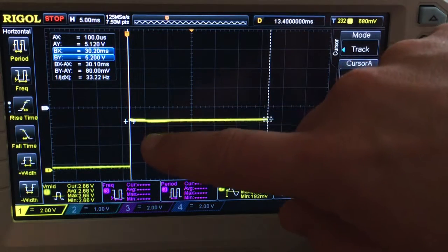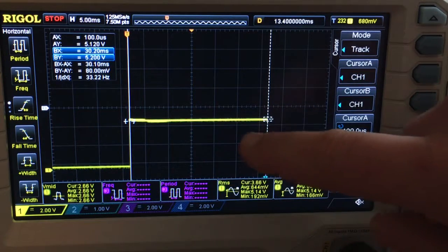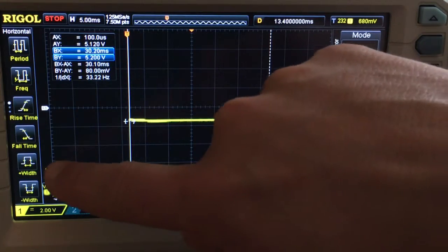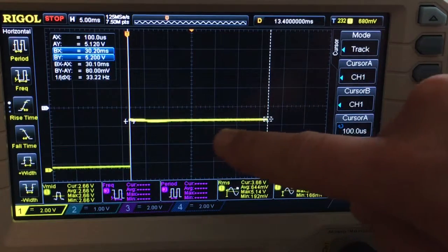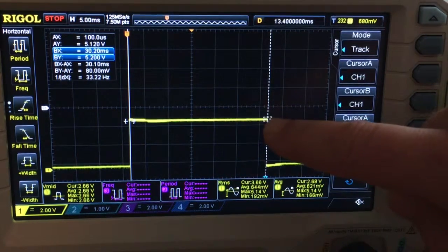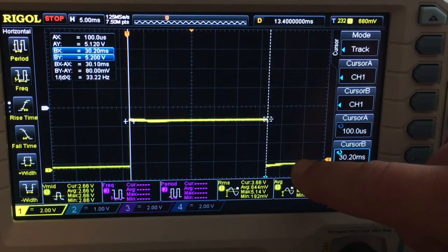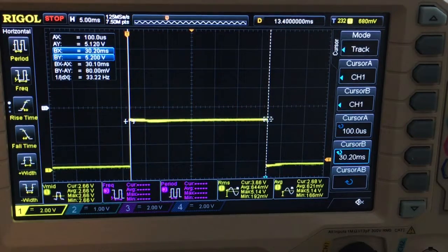On the other hand, if this was in bulb mode, then the camera would slave to the exposure time duration as specified by this signal. So in that case, the camera is doing nothing, nothing, nothing, signal goes high, camera exposes for 30 milliseconds, and then ends its exposure on what's referred to here as the falling edge, or the falling of the signal back down to 0. And so this is how triggering works. It doesn't just work this way on cameras, it works this way on any other device. And in fact, many devices even use protocols based on this that just switch on and off at very high speed.